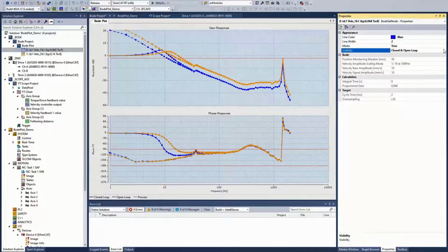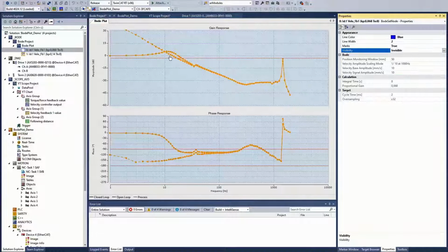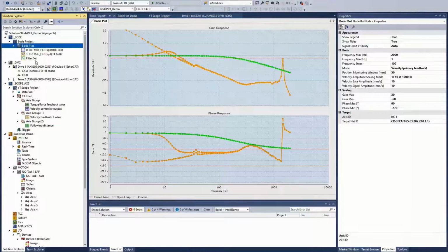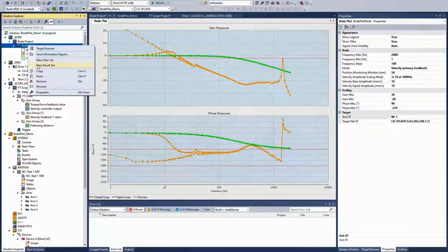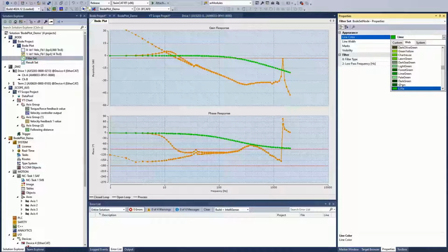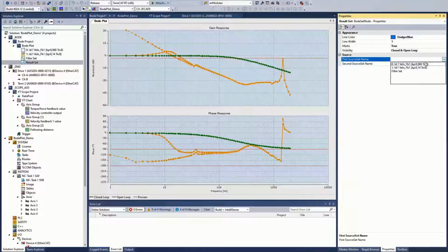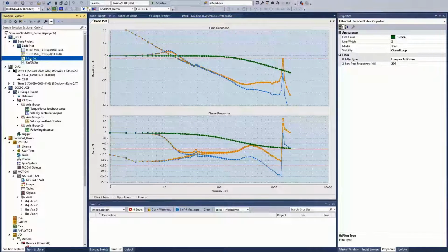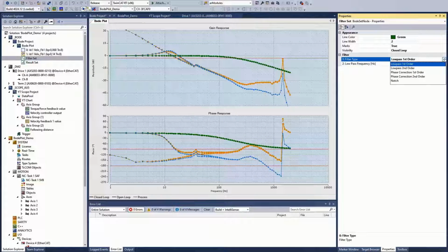And we have to do something because this spike is causing some sound, unstable behavior. The axis is not uncontrolled, but unstable. We add a filter, we add a result, and then we have the option to combine our measurement with a filter and simulate a filter to see which filter makes sense to eliminate this spike. Therefore, we have to choose the correct filter type. A notch filter makes sense.